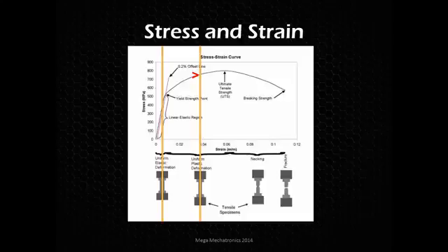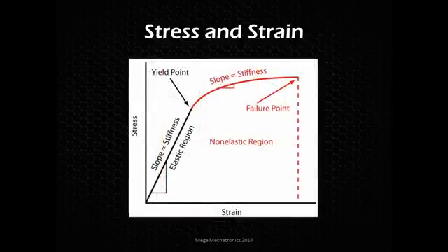change in length. And then some materials will experience this where you require that same maybe 650 MPa, and we're way over on the strain, and then until it fractures, and that's our breaking strength right there. So there's some important attributes to the stress strain curve that we need to understand.